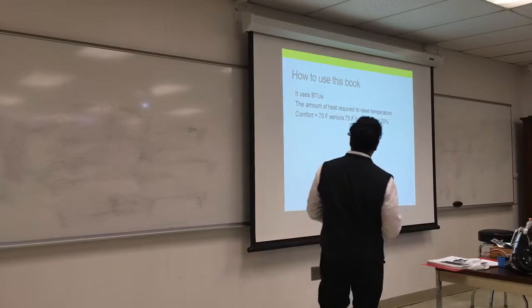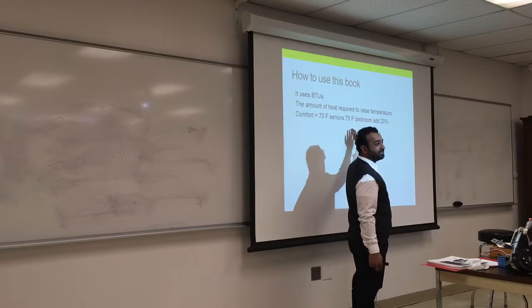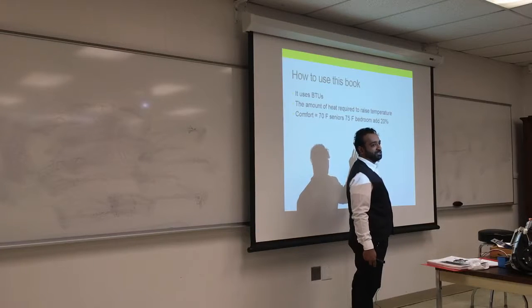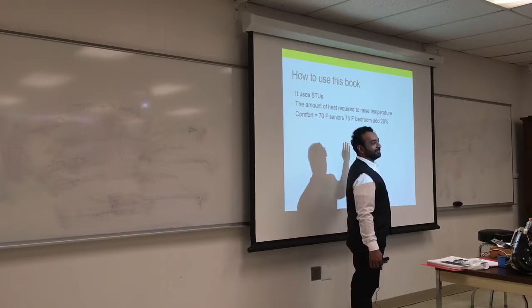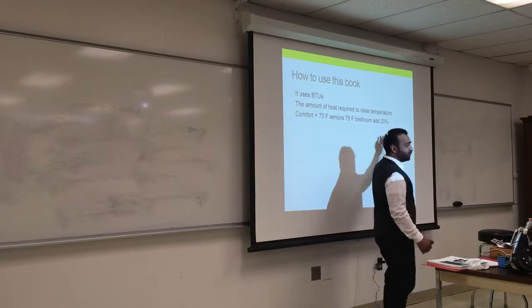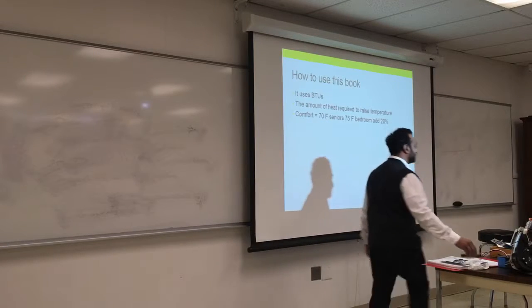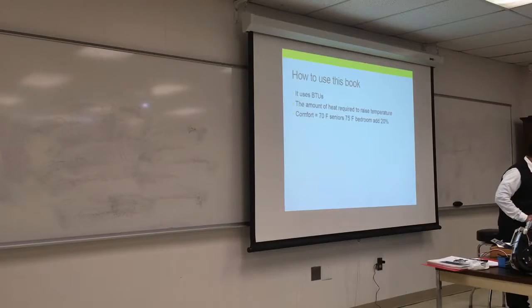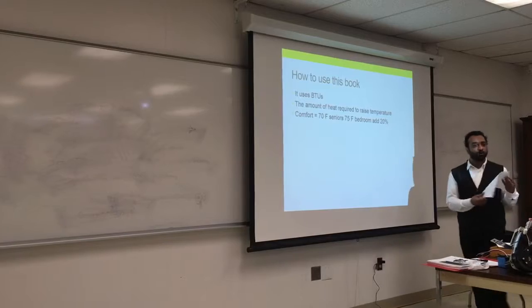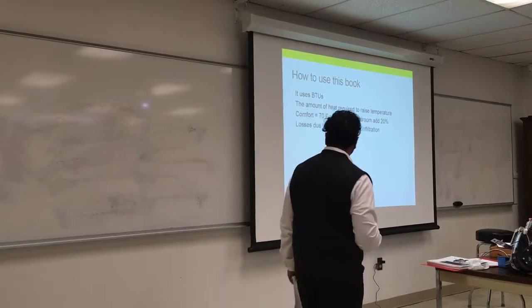And our comfort level is 70 and sometimes 75. So when I set your inside temperature at 70 or 75, don't go extreme and set it at 60. That's not realistic. 60 is very cold. So 70 or 75. And for bedrooms or bathrooms, you add 20%, and it says that on the sheet. If you look at it, it's a bathroom at 20% because that will go towards evaporation. Stop me if you have any questions.